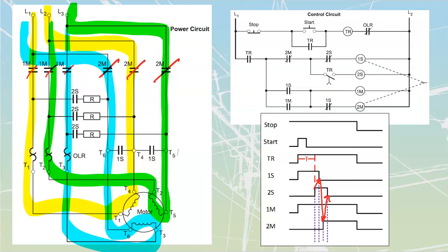Once again, timing diagrams really are going to become so critical. It's so easy to otherwise get lost and build yourself into what you think is going to be a short circuit inside of the circuit or things like that. If you cannot read these, I can read this one through years of practice without having to have that timing diagram that's showing me click, click, click, the steps that this thing is going through. But it is still easier for me. It's not that I can't do it off of this, but I'd way rather just build this, because it's only going to take me a couple minutes to go through this control circuit, build this timing, and then carry that over to my contactors and actually understand what's going on inside of that circuit.